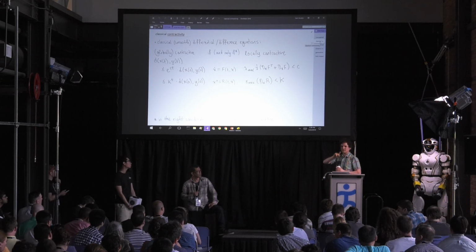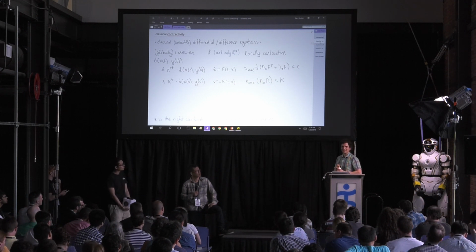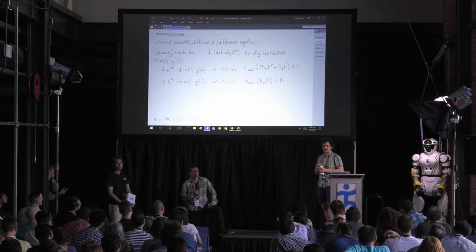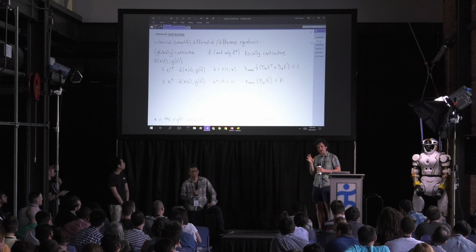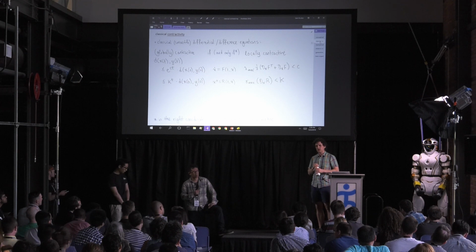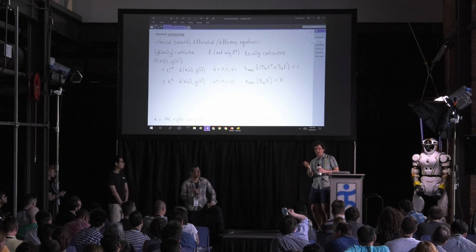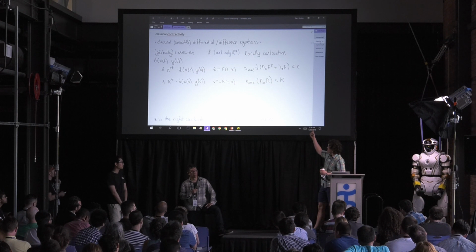Well, let me say this. I have these results for the classical case. I can look them up in textbooks and established papers. In the classical case, this is inevitable if we want to get the kinds of behaviors I think we want, which is that I'm going to have a closed loop system at the end of the day, after I've done all my careful design and engineering, that rejects perturbations, that I can modify my inputs slightly or parameters slightly, and it doesn't dramatically change the behavior of the closed loop system. And in that case, the classical theory says that, yeah, actually in the right coordinates, your system is going to have this contractivity property.